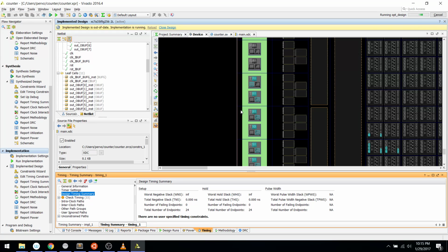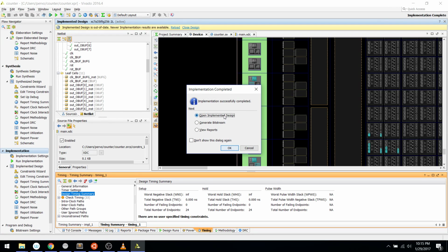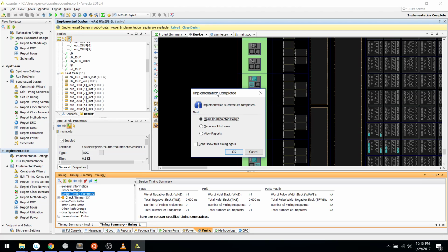Yeah, so in my projects, I've been using an open source compiler called Verilator, which generates C++ code that represents a cycle accurate emulation of the code. It can have issues, especially like it's not a perfect replacement for a full flow like this, but for a lot of the basic programming and design stuff, it's more than sufficient. You can simulate quite complicated chips at a fairly high simulated clock rate. Like full systems on a chip, you can maybe simulate at 100 kilohertz or something, which is enough to do boot up and trace testing and stuff like that on real chips. So it's very convenient, even if it's not a perfect litmus test for whether it's going to work in hardware.